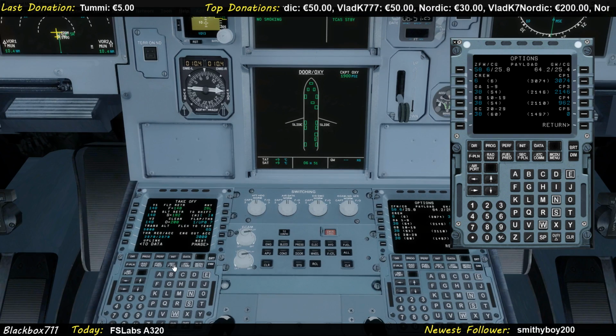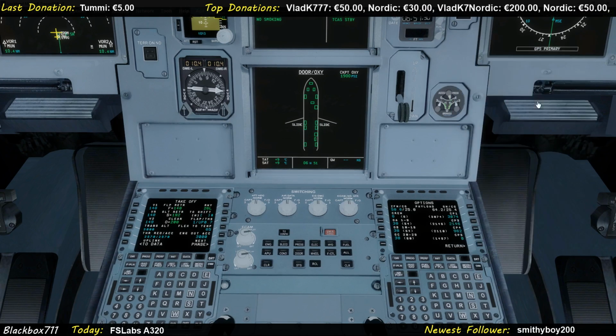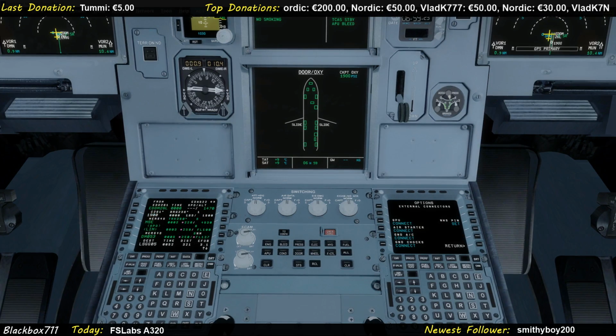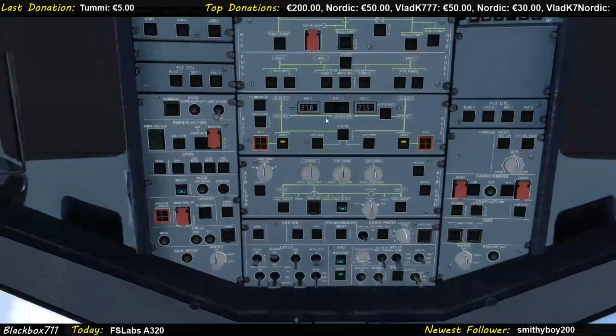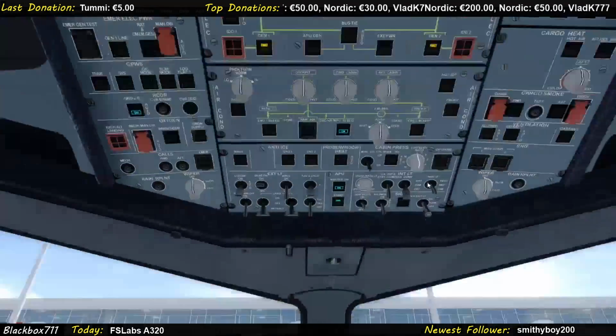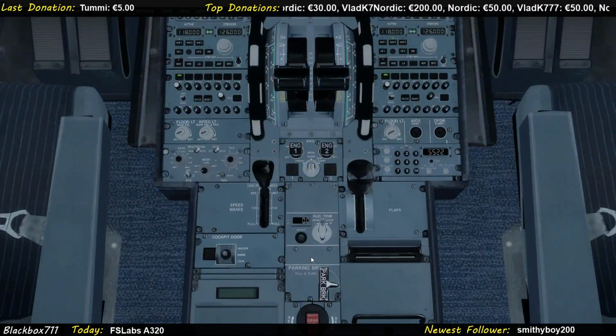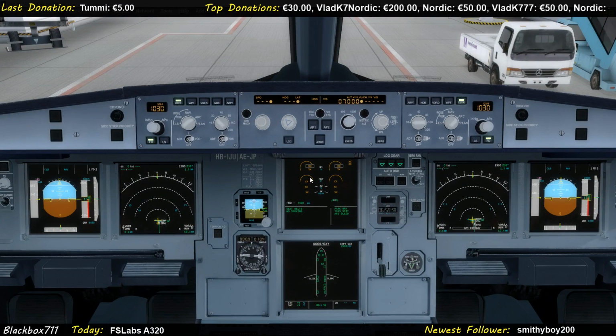Once the secondary flight plan function is inserted, we'll use that and copy the actual flight plan. Right, lots of stuff, right, guys? Okay, so the checklist. We have cockpit operations completed. Signs are on auto. Fuel quantity 5,560 kilograms. Altimeters 1030, 1500 on both sides. The windows and door are closed. Beacon is on. Thrust levers idle, and parking brake is presently off.